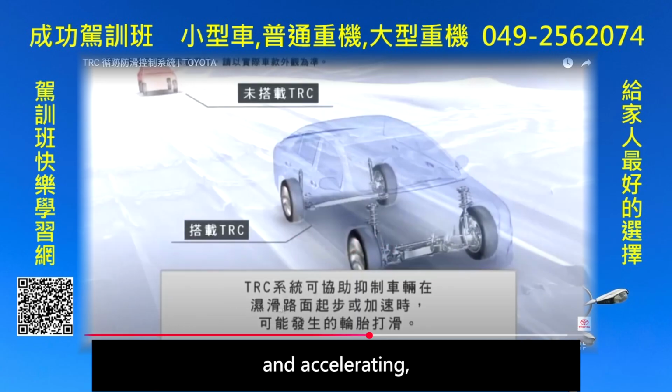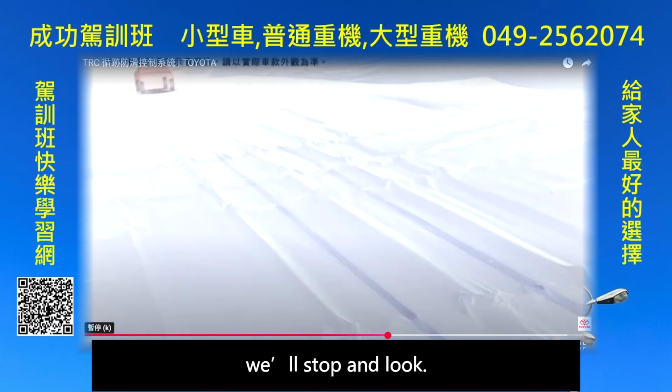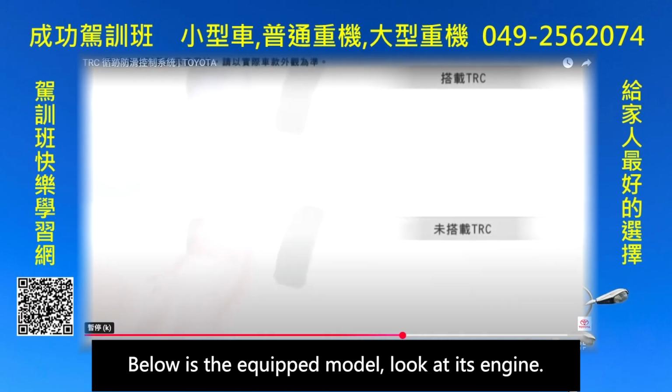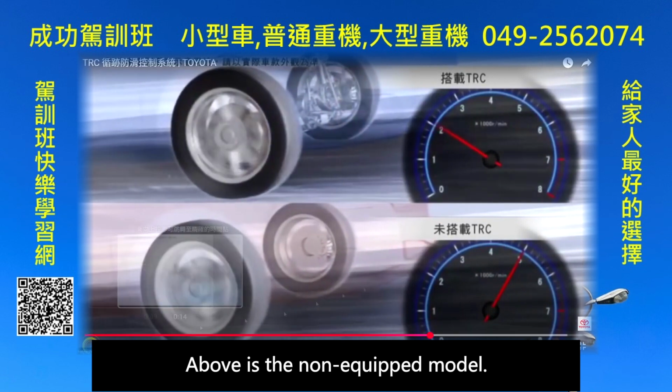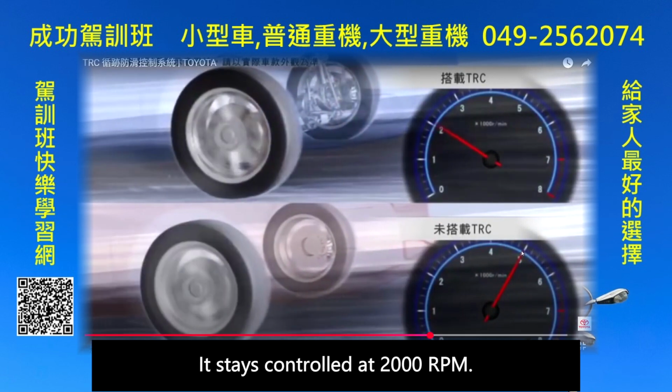and accelerating, tire slipping may occur. We'll see that with and without. We'll stop and look. Below is the equipped model. Look at its engine. The tachometer reads 5,000 RPM. Above is the non-equipped model. It stays controlled at 2,000 RPM. So when you step on the gas, it detects the slipping phenomenon. It will slow down your engine RPM. From here we can see the bottom shows the controlled throttle. Original state. After that, it has stopped.